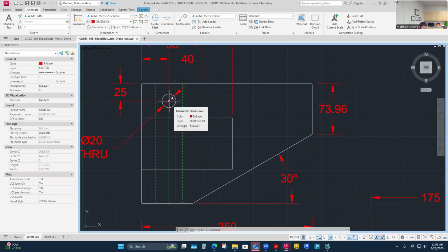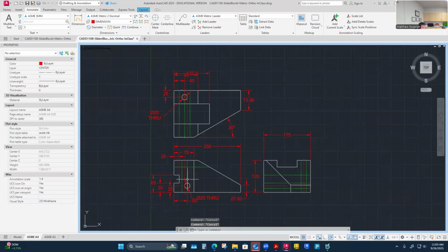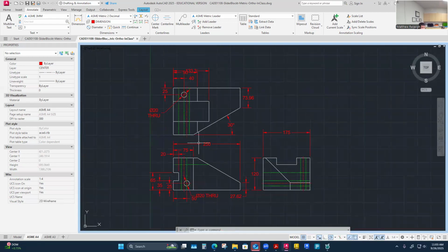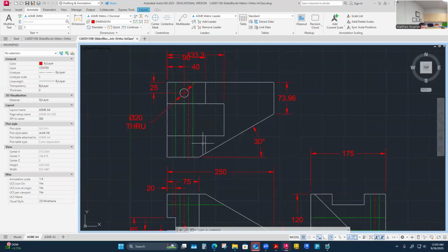What if my bit varied, or what if I was hand drilling it rather than a machinist milling or turning it? Well, there's a huge difference in accuracy, and in the future, we'll also hold how symmetrical or how cylindrical this hole could be. There's a lot of constraints I can put on that to control it. And long, deep holes, I have to maybe control a little bit more accurately, but not right now. That'll work. It's just hold it straight and through.